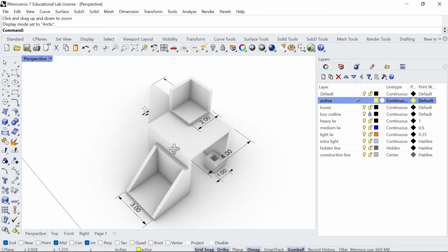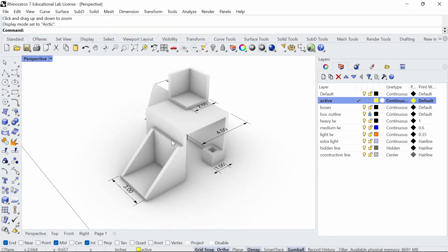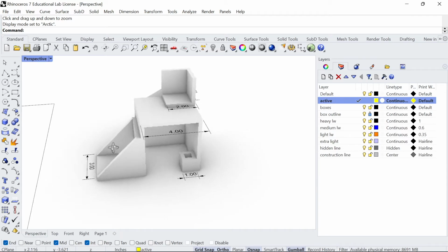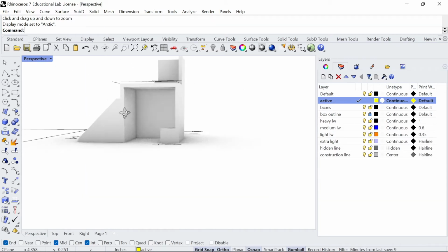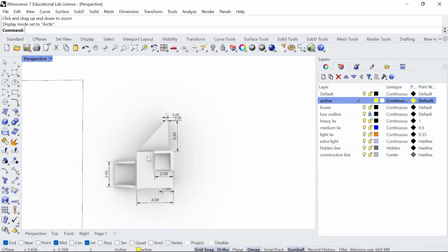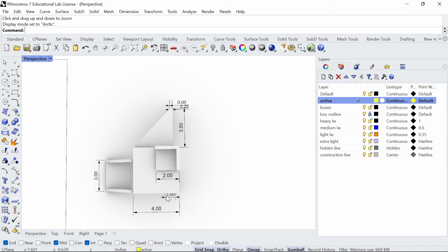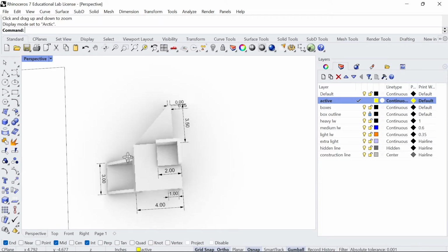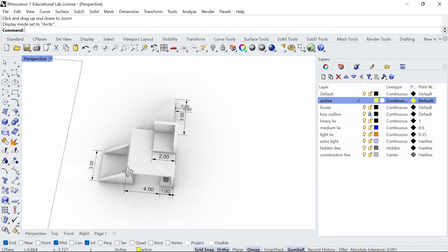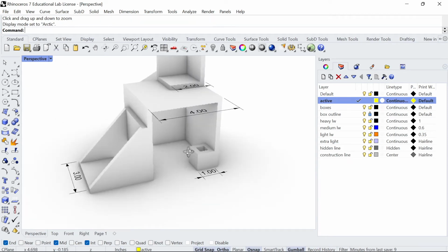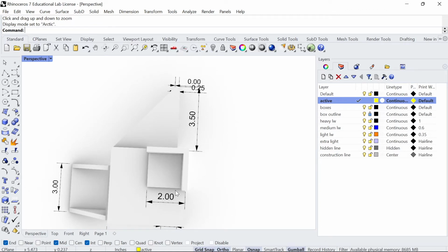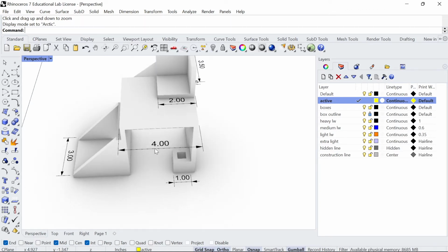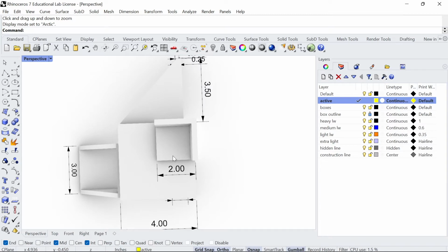Again, you won't have a 3D model, but the way I'm understanding this, you're arranging your boxes in any direction that you want to create a complex object. And really what you want to do is draw the top view first. So you can see that you have the main 4-inch box, you have a 2-inch box on top of it. To the side of it, touching the ground, you have this other 3.5-inch box, and then also a 3-inch box to the left of it. And inside the 4-inch box, you have another box, which is a 1-inch box. So what you don't see in this view is that 1-inch box. So that's going to be seen as a hidden line, and you'll understand it when we get to drawing it.